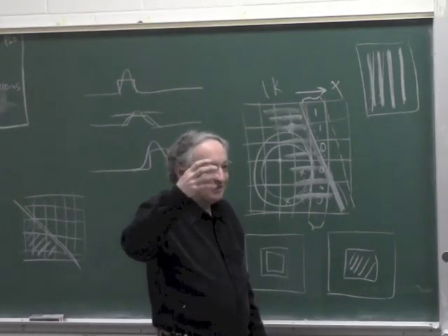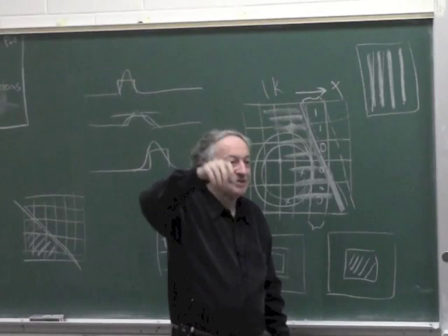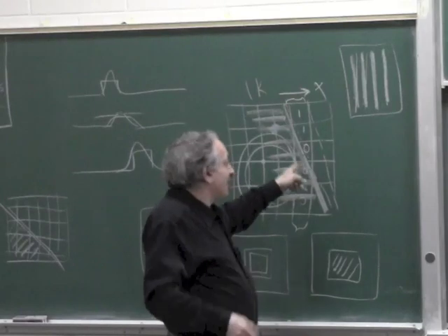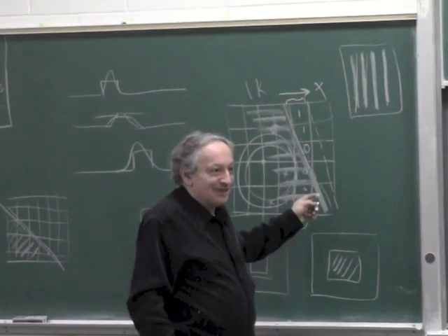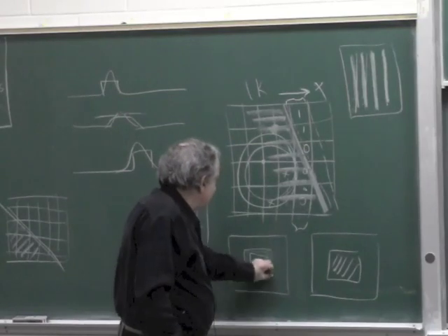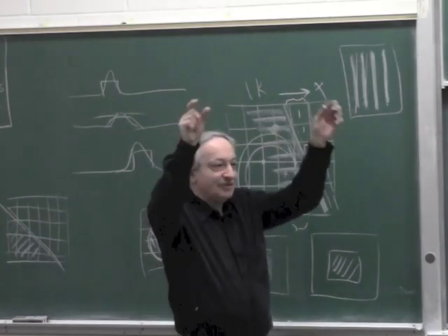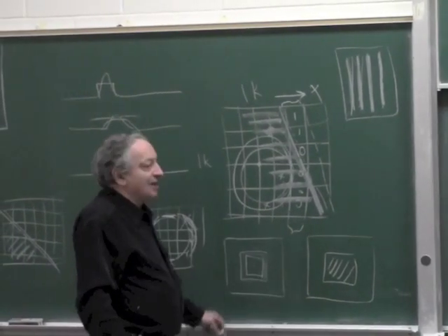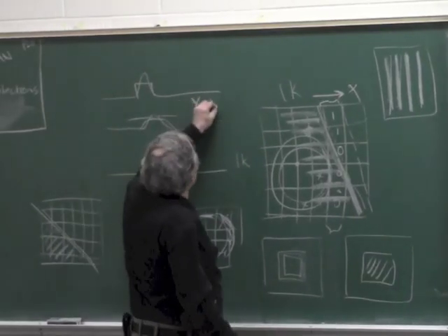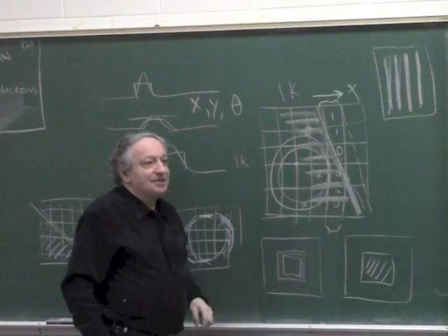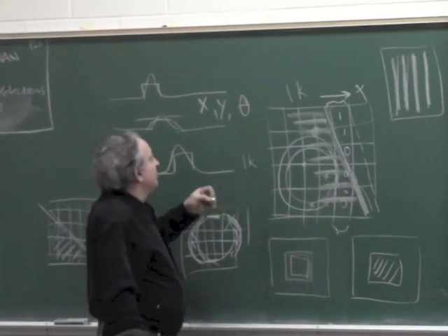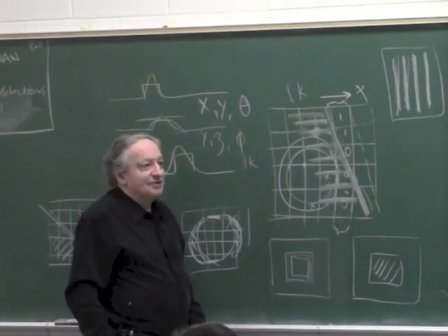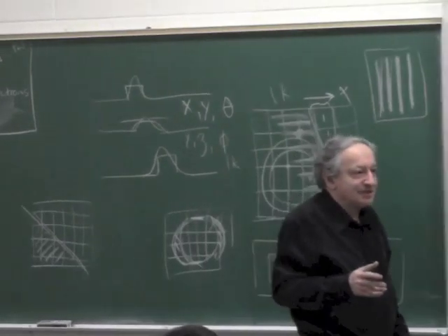So if you look at a crane to know where the tip is, and the crane has some headlights on top, this is a bit dangerous because the camera can pick up some lamp and think it's a target. But if you use this as a target, it's hard to believe there'll be an object lit in the form of a square on the tip of a crane. So you can see that the same camera will measure x, y, theta, and all what you need is a second camera from the side, and it will measure, say, y, z, and phi. So you get a 6-degree of freedom sensor with two cameras.